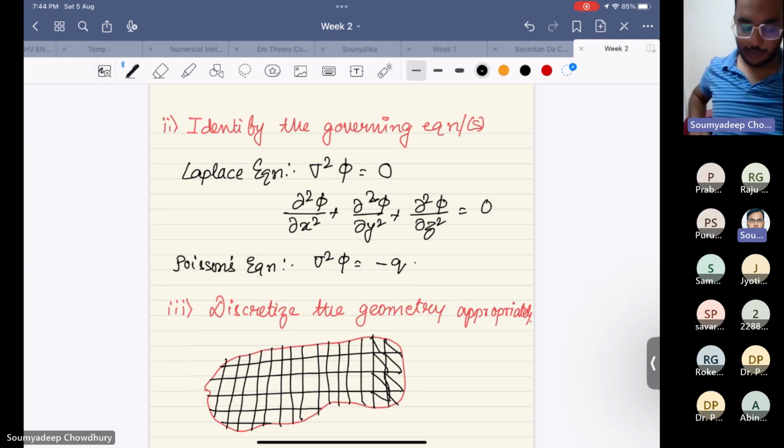So now the problem is why we do this. First, you need to understand why we do this. Because this is an irregular geometry, right? We cannot apply any of our governing equations to this kind of geometry. So we need to discretize it into smaller elements where we can individually apply our governing equations. To apply any governing equation, we need a well-defined geometry like a rectangle or a triangle. That is not possible within this irregular or undefined geometry. So that is the main reason for discretizing or dividing it into smaller rectangles or smaller sections.